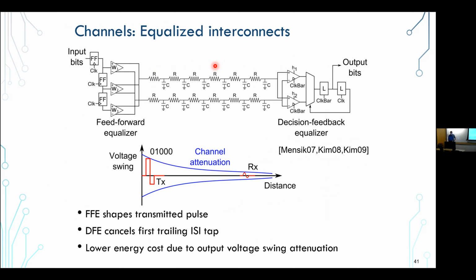Of course, one thing to keep in mind, these are all high SNR situations. You don't want to be losing bits because your swing is too small, and now all sorts of power supply noise, thermal noise, all of that stuff comes in, and with some probability it ruins your bit.